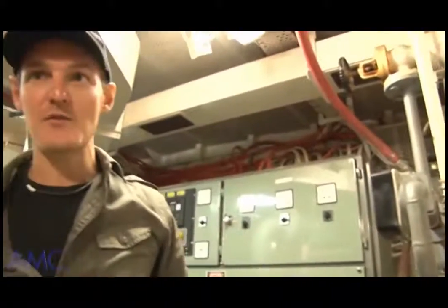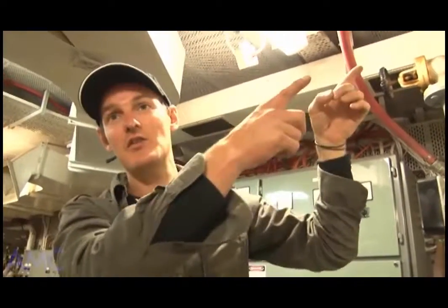We're looking at our day tank low level alarm. That's a float switch. If our tank level drops below that point, then it's going to set off an alarm that it's time for the engineer to pump up the tank. We've also got a high level float switch, and that's up in this corner here. Conversely, if we overfill the tank or we forget to shut off the transfer pump or the purifier, then it's going to give us an alarm that our tank is nearing its top.